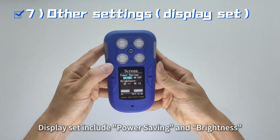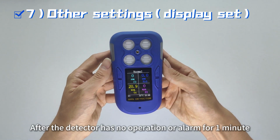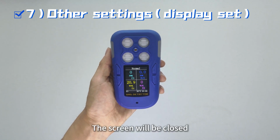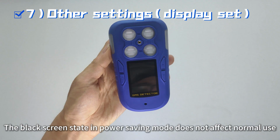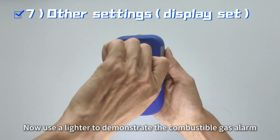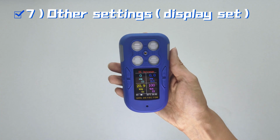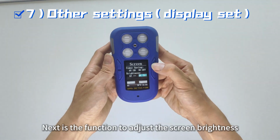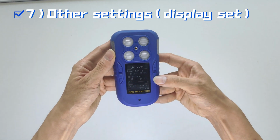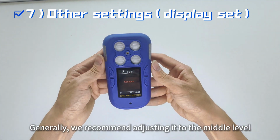Display settings include power saving and brightness. When the power saving mode is on, after the detector has no operation or alarm for 1 minute, the screen will be closed. However, the black screen state in power saving mode does not affect normal use. Now use a lighter to demonstrate the combustible gas alarm. Next is the function to adjust the screen brightness. Generally, we recommend adjusting it to the middle level.